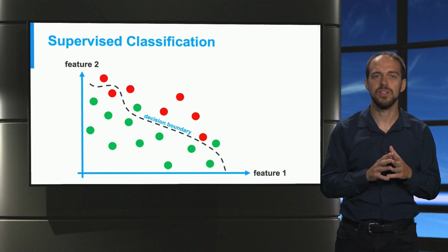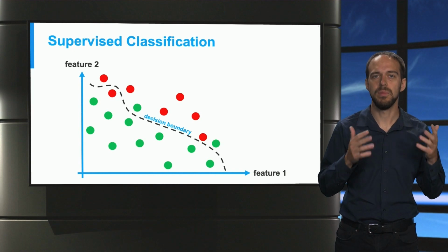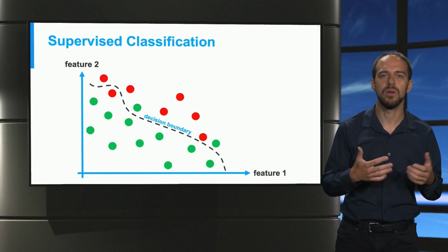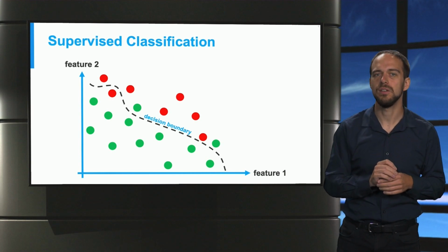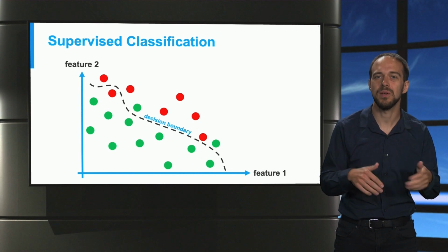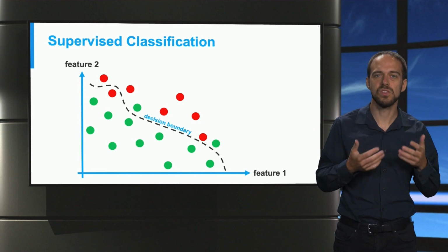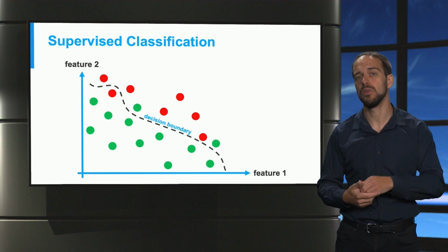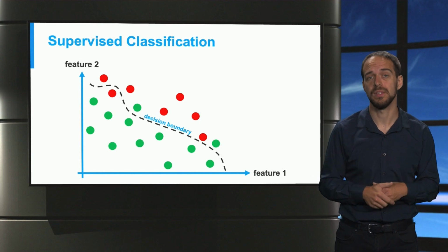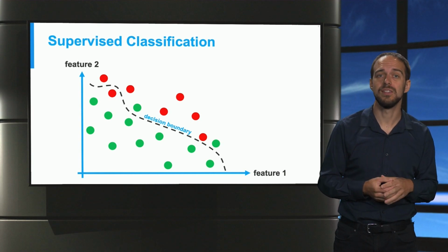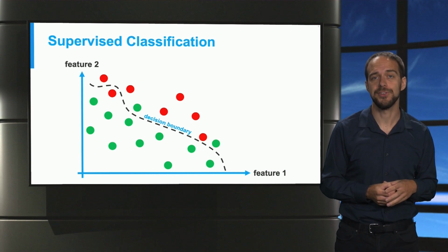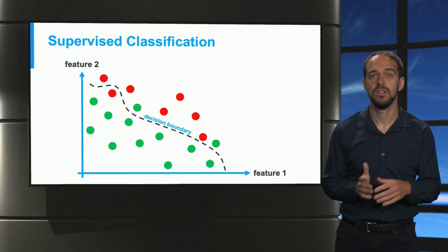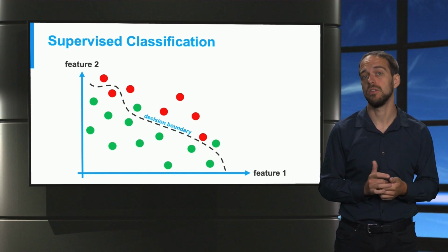The features are the dimensions of the power system variables. The power of a generator could be one of the features. Think about a wind park that generates power. If the generator's power is very high, we may expect that the power system is under a lot of stress. So the system or equipment failures are more likely to lead to power blackouts than when the power of the generator is low or lower. Therefore, we try to learn a decision boundary before real-time operation and then use this trained decision boundary to classify green from red, to separate secure from insecure operating conditions.